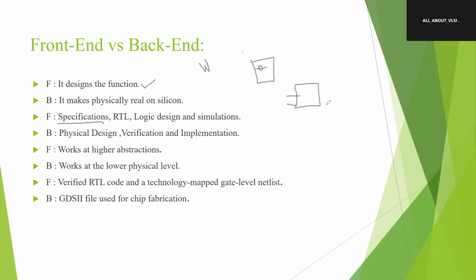So we are giving some specifications. After that, RTL people start working on that logic, working on those specifications. We write the code using Verilog and VHDL according to those specifications. After the logic design, we simulate that logic using clocks. I'll draw the clock thing, right? We observe the simulations and verify the logic.